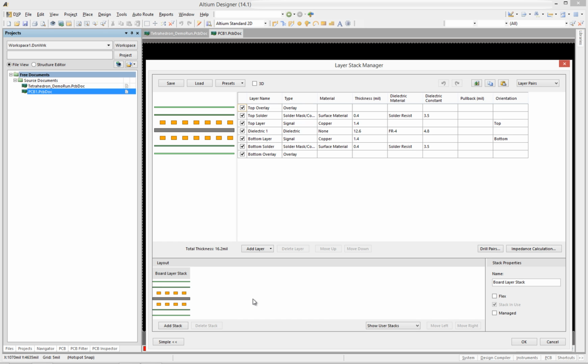So for example, if you have a board, and let's say the centerpiece has 8 layers and the Flex Rigid has 2 layers, and the peripheral boards that are going to connect to those Flex Rigid are 4 layers, you can actually define each one of those. This would be, for example, your main stack, your flex stack, and another rigid stack here. Now I'm not going to go through the motions of that. I believe that warrants probably a video all its own. But what I'm going to do here is load in an existing stack up that came from one of Altium's examples.